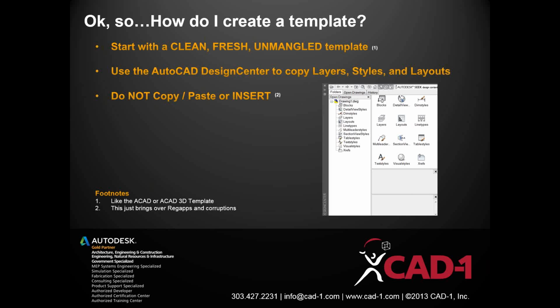Okay, I've been asked, if one knows ahead of time that every drawing is going to have to XREF specific drawings, is it possible, and a good idea, to attach XREFs? Oh yeah, definitely, Ivan. As a matter of fact, title blocks, that's a common one. I've got a company standard title block. We use that in all of our projects. We like to have it built up specifically for our company with a logo, and they want to XREF that in. Oh, yeah, definitely.